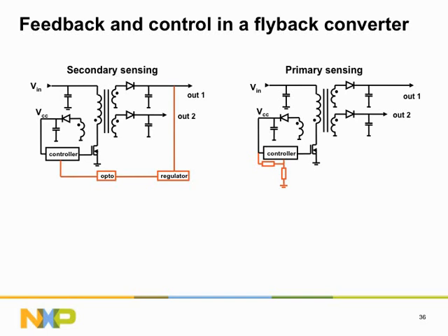Only transformers that have a perfect coupling between the secondary winding and the auxiliary winding will produce an accurately regulated output voltage. Unfortunately, these transformers do not exist, and constructing a transformer with at least very good coupling between the two windings will result in a complex construction that is relatively expensive. Therefore, reduced regulation accuracy must be accepted when primary sensing feedback is used in an SMPS topology. In practical circumstances, primary sensing can be a good choice for low-power switch-mode power supplies, but for most high-power circuits, secondary sensing will be the preferred method of feedback.